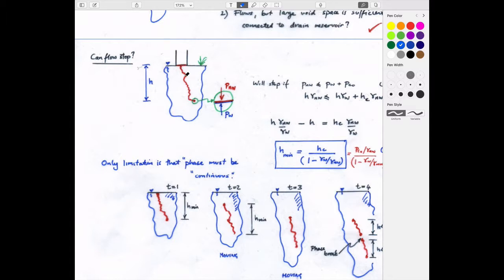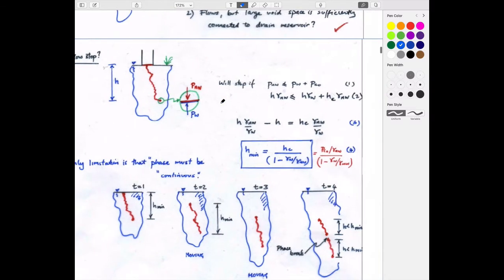It doesn't matter that we're in a porous medium. If we're simply connected from the top to this point by the red fluid, it's exactly the same as that existing as a column within a swimming pool, maybe in a test tube, if you like, in a swimming pool. So we can calculate the pressure at this base merely by the height of this fluid multiplied by its unit weight. We can calculate the pressure in the water, again, by the depth multiplied by the unit weight of water, and that's the pressure balance at this point.